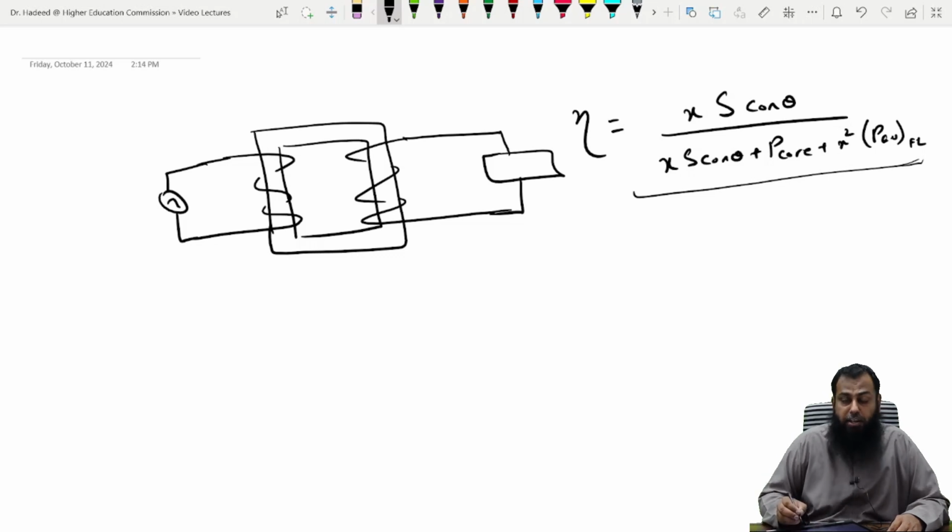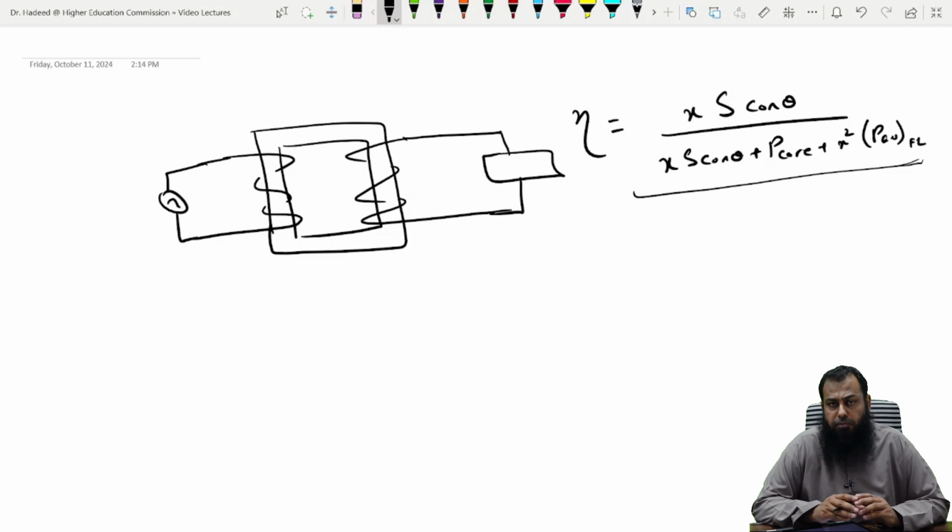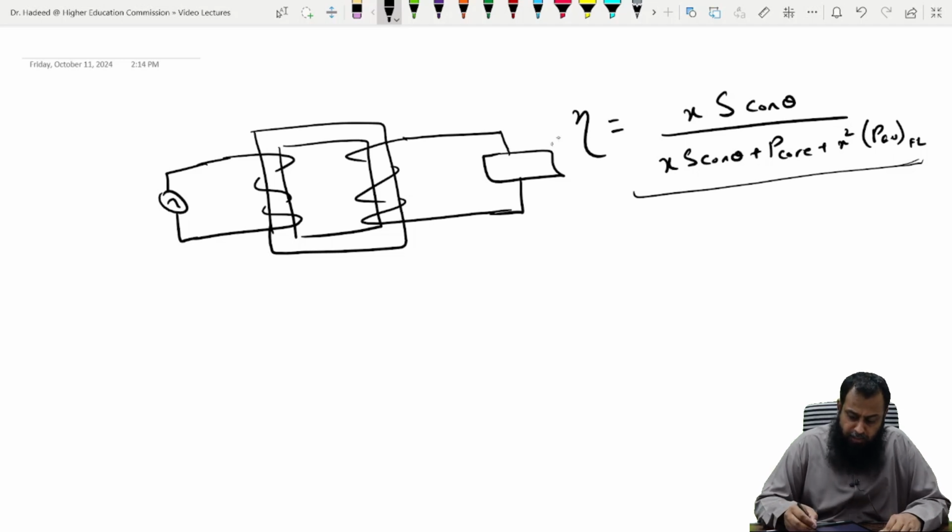However, if we have a transformer which is actually a distribution transformer, there we have a problem. According to the load profile, the nature of the job, the nature of the people living there, the school schedule and various other parameters, they actually influence the amount of current drawn from a transformer throughout a day. And therefore, this loading based efficiency of a transformer may not be a very good indication of the efficiency of the transformer.